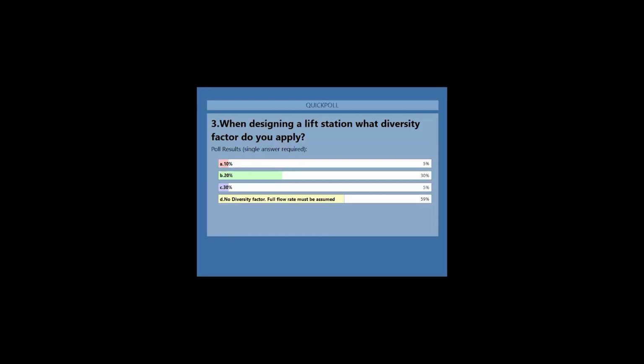The reason I say for a pH system, it's typically 20 to 30. If you have a known process stream that dumps, that's just your diversity factor. So if you always have a certain flow, or you always have a certain process or tool that continuously dumps, then obviously there's no diversity in those cases. Diversity factor comes up when you have more fixture-based designs going on as part of your pH system.